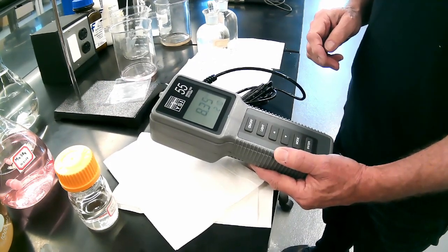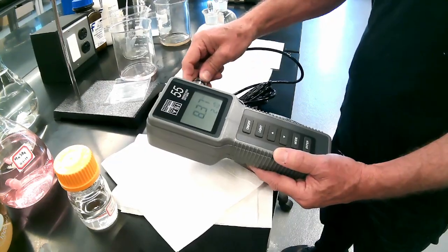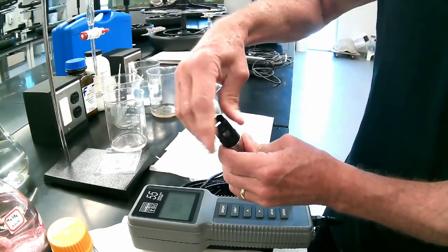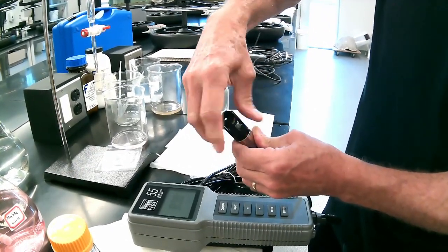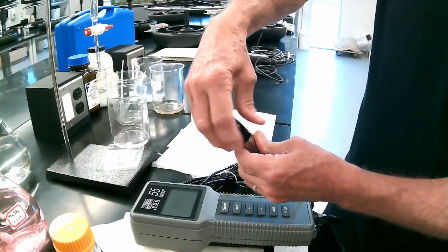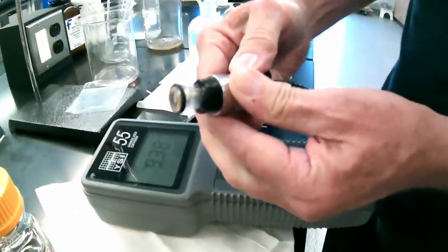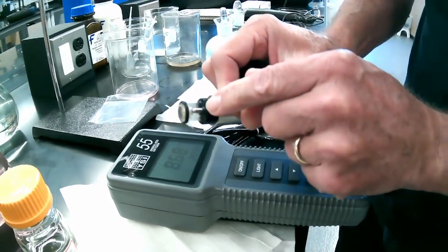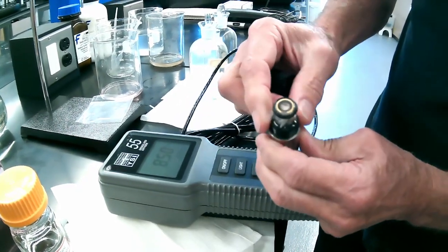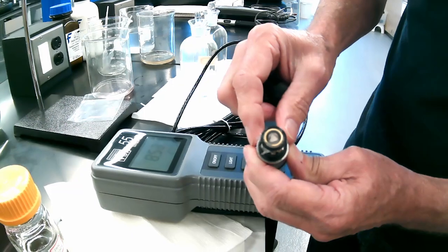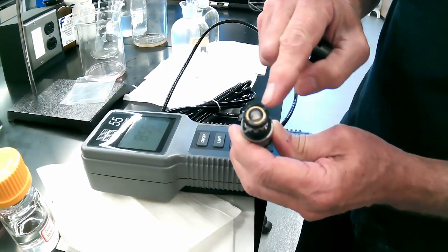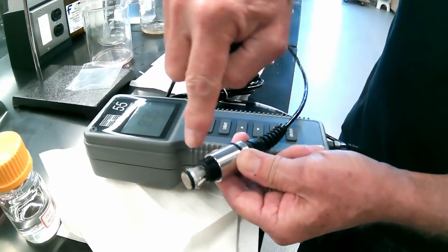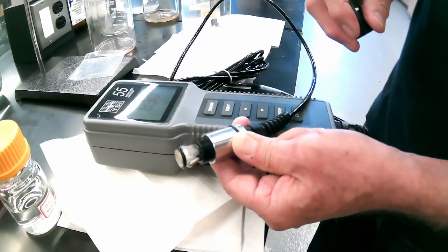All right, so we can take this. Here's the probe. This is the probe that we were talking about before. It's got a little guard on it so that you don't damage the end of it. We can take a quick look at how that's put together. You can see the little gold cathode in there, the little wire that runs down there. This is the temperature probe that sits here. Here's our membrane on the outside, and underneath there, although you probably can't see it because it's filled to the top, there's electrolyte solution inside this little area, and the anode sits down. It's that little gray part that you see down there in the middle.